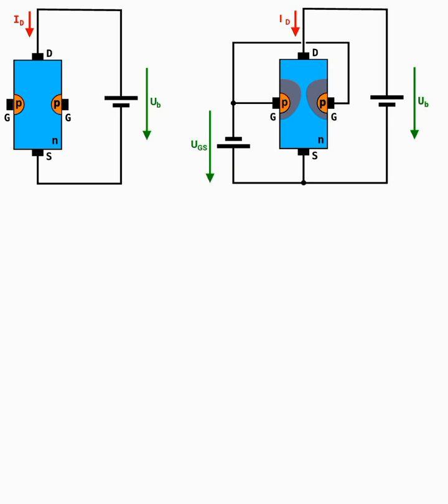Now similarly, the source pin of the N-type material is connected to the positive potential, and the gate is connected to the negative. So this side of the PN junction is also reverse biased, and that's why you see this depletion region right there.